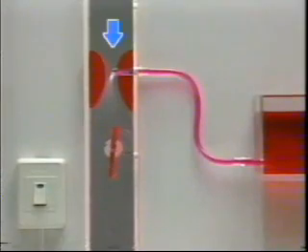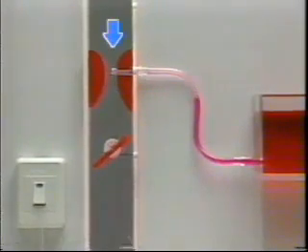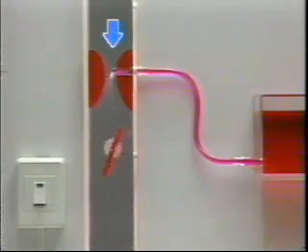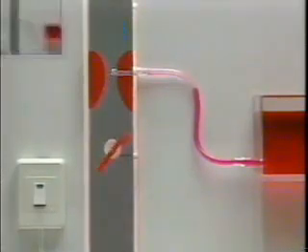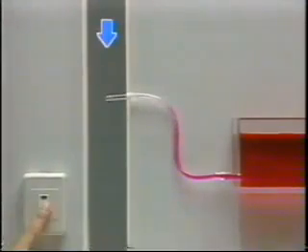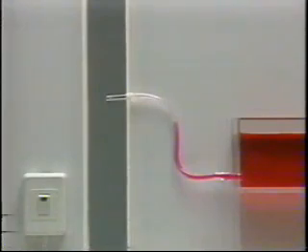This is a model used to demonstrate the principle behind the carburetor. Air is blown in at the bottom, creating a vacuum which forces the liquid out. We will explain the functions of the carburetor using this model. First, we will conduct a test in which the nozzle of the fuel pipe alone protrudes into the air tube. If a vacuum is applied to the bottom of the tube, we see that the fuel rises in the pipe a little, but due to insufficient air pressure, enough fuel will not exit the pipe.